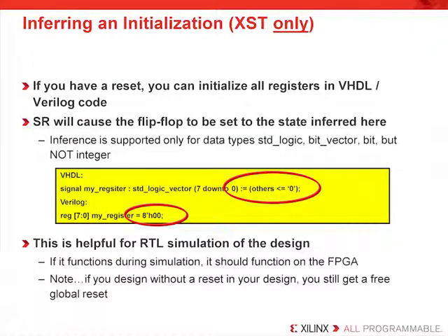Initialization of flip-flops in an FPGA is important for behavioral simulation. In this example, we have behaviorally coded a reset in our HDL. This will allow the simulation to show clearly what condition each flip-flop is in after power up. Synthesis tools will react to this HDL code. Most people assume that this is unsynthesizable code, but it will in effect set the initialization value of the registers because that is tied to the register's primitive chosen by the Xilinx Unified Library.